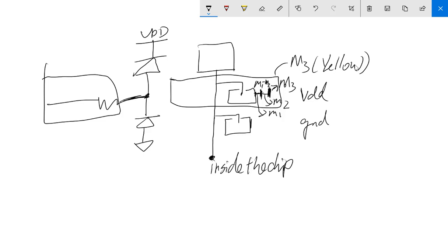So this is being connected to ground, and this should be a metal 1 to metal 2 connector, and this is metal 2, right? And this is metal 1. And then you need another connector, that's a metal 2 to metal 3 connector, and it's going to drill a hole from metal 2 to metal 3, so you can draw a layer.